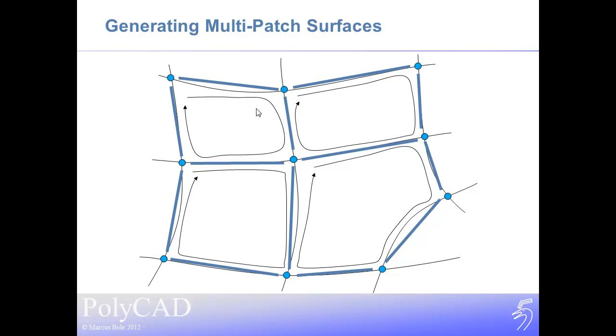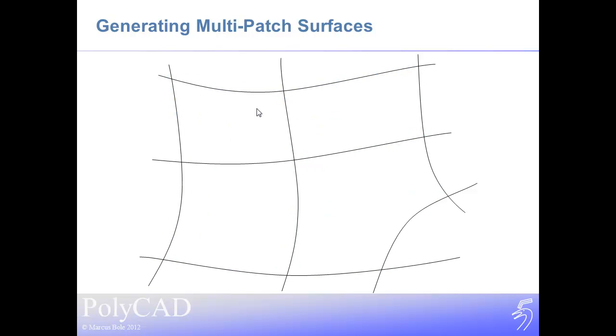So what we do next is process this assembly of curves and vertices and edges. The first thing we need to do before we can generate a patch is generate the tangent information. And this is achieved by taking each curve in turn and assessing the curves that intersect with it and generate a tangent ribbon along those edges. That tangent ribbon is then subdivided by the edges that it exists within, so split down to the curves that cross it. And the tangent information for those individual edges can then be projected into the face area, and from there we can blend our surface as demonstrated previously.